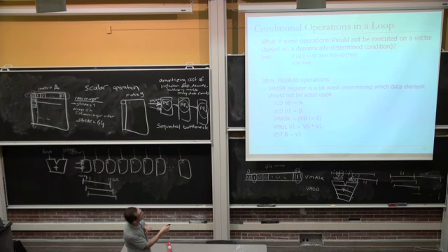This tests each element of the vector register and sets the mask for each of the vector elements. And this multiply later on is essentially multiplying A and B, which are stored in vector registers 0 and 1. It multiplies those elements whose mask bit is not set to 0. Make sense?